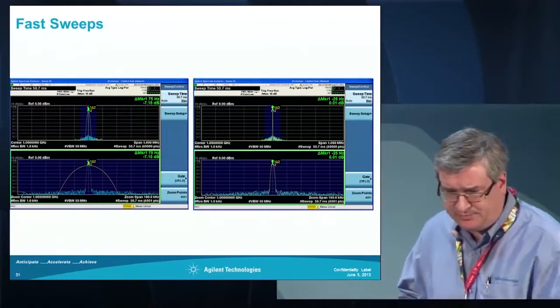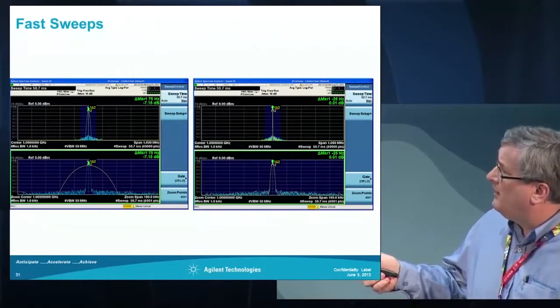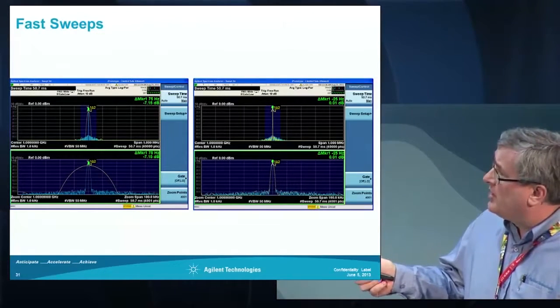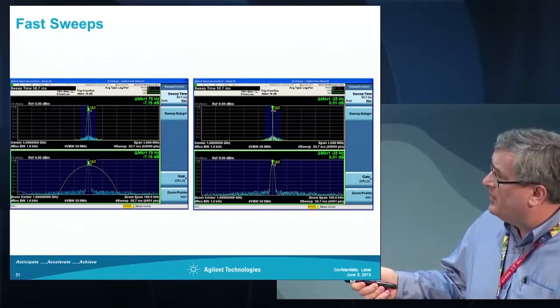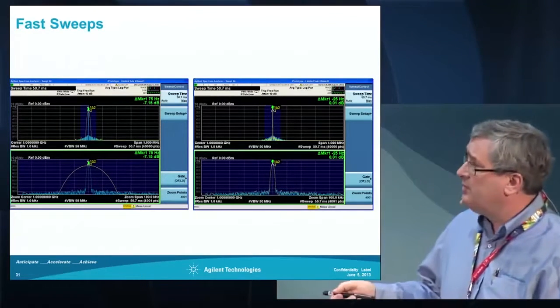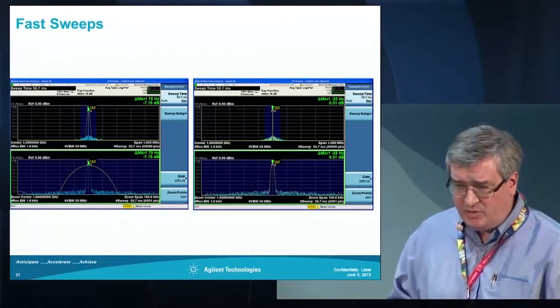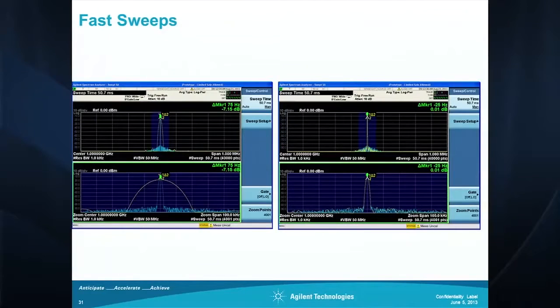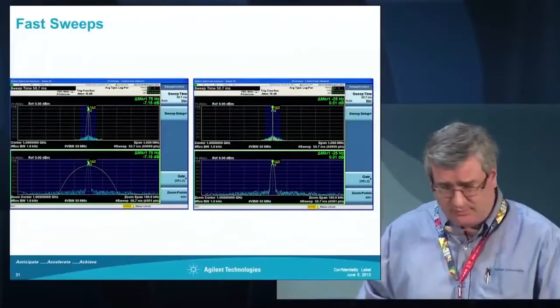So here we have a tone with a resolution bandwidth filter. Here at the regular swept speed, and here is as we oversweep. You see it's got this huge bloom because we're oversweeping the instrument. Here it is where we do the digital pre-distortion curve. Here it is referenced with the normal. And here you'll notice, boom, it's now completely recovered the proper resolution bandwidth.